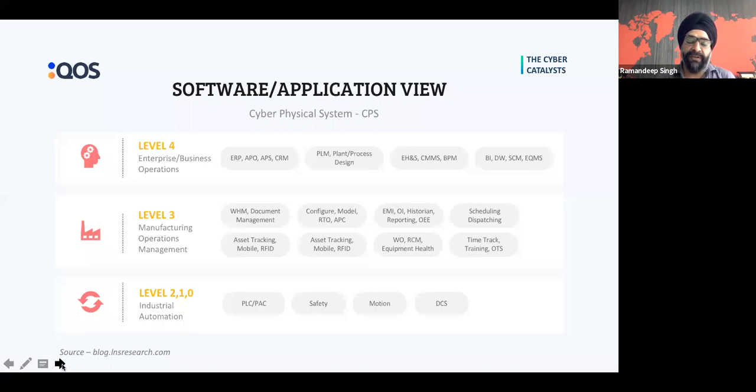So it's sometimes also called the Purdue architecture, in which you see devices like DCS and PLCs, which connect to those end IEDs and RTUs to distribute the logic or the process information so that it can be automated by virtue of actual physical devices like safety valves, temperature gauges, pressure measurement instruments, or the motors or the actuators that are giving the power or the motion to different components in the process of manufacturing or power distribution or power generation or oil distribution or oil generation. So those all get classified as level 0, 1, 2.